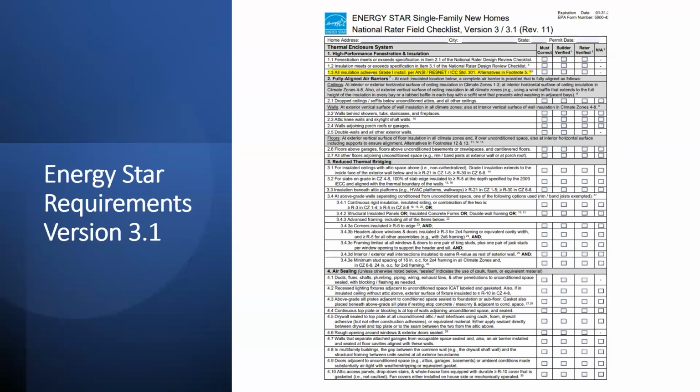The reason I put this in here is because we're seeing more Energy Star being used as a pathway. When you're out there and the city officials are looking at it, and you know that it's being done as Energy Star because you've seen the permit documentation, just know that they need to meet grade 1 on all insulation components except on the exterior wall and attic walls. If they're using R3 board on the outside in this climate zone, it can be grade 2 and still pass. Grade 2 batts are permitted to be used in floors if they fully fill the cavity, touching all 6 sides. So as long as they're doing that, then those 2 things are permitted. That's why they put the footnote in there for those different areas where it can be done.